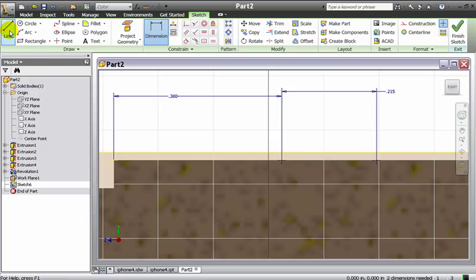Now what I'm going to do is grab my line tool, and I'm going to lock onto this point and just move above it slightly. Just a little bit above it, but make sure that you're on the same line, a perpendicular line to here. Click, and I'm going to move this down into the body of the phone right there. Now I'm going to dimension from the point to the bottom of this, and this distance right here from the point to the bottom of the line I want to be 0.04.